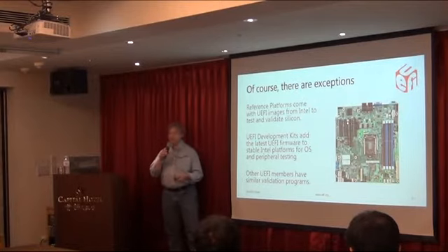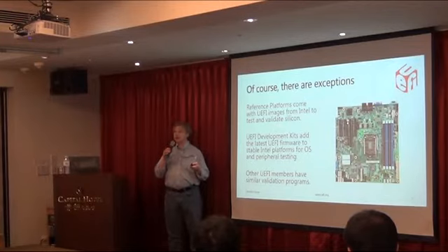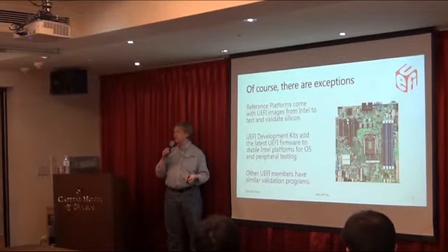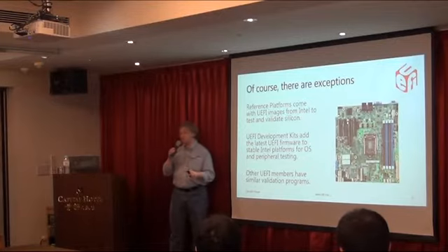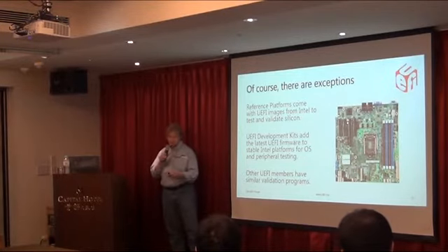And again, those have a specific version or a specific purpose for testing the reference, testing the silicon. They're used to more exercise the board than they are to provide shipping firmware. So if you had a reference BIOS, you would never want to give that to a customer. It's kind of slow, it has a lot of crazy messages in it, it has options for bits that nobody understands how they work unless they read the documentation, and you don't want the customers to ever touch those bits. So yeah, never let them touch those bits.